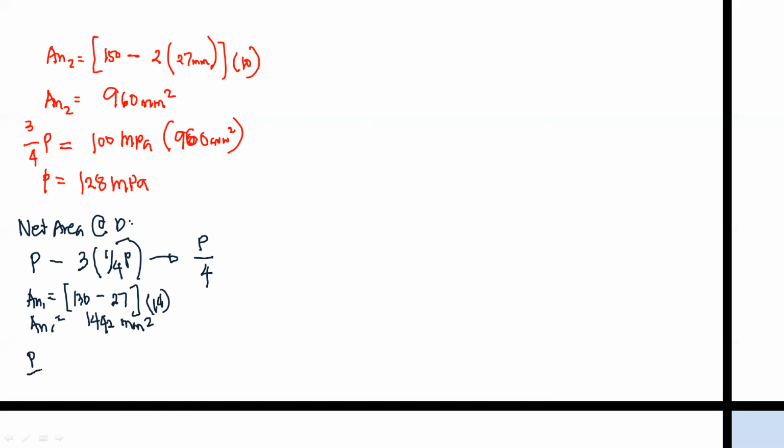And having the force of P/4 times 100 megapascals times 1,442, this would give to P equal to 576.8 kilonewton.